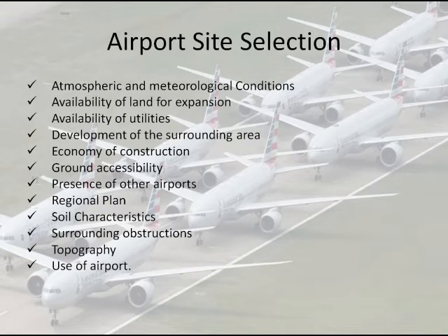The detailed analysis of the available weather records of all the potential sites will be helpful in recommending the site which has the characteristics commensurate with the aviation needs. The wind data should also be studied, and to have a minimum blowing of smoke from the city, the site should be located on the windward direction.